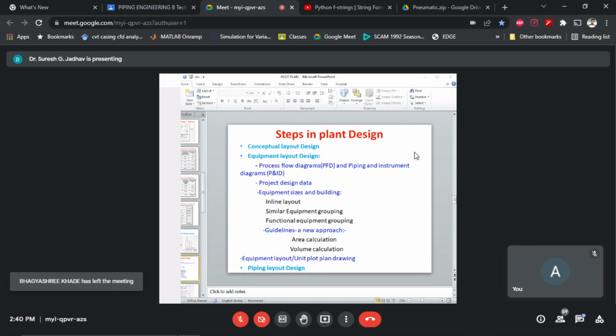Generally, all equipment and facilities that need floor space, access, removal space, cleaning areas, storage space, and handling facilities are outlined. Good layout design minimizes the cost of operation and maintenance. Access is the most important feature to be considered.